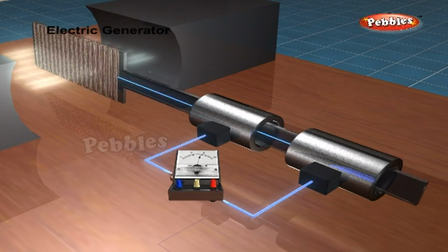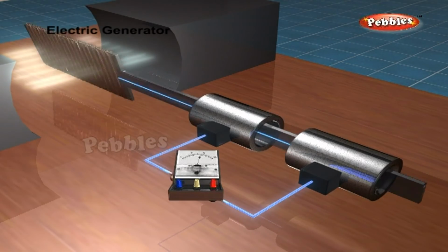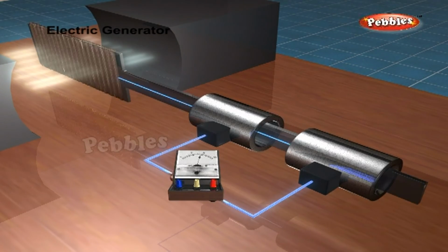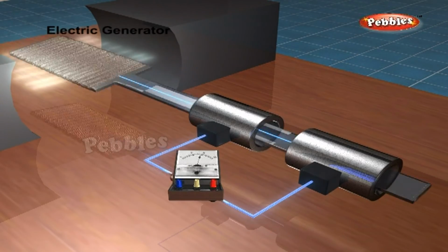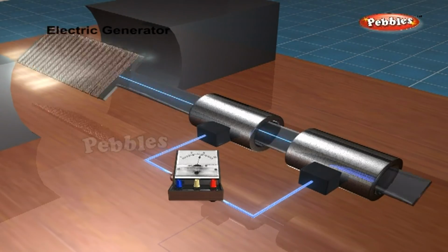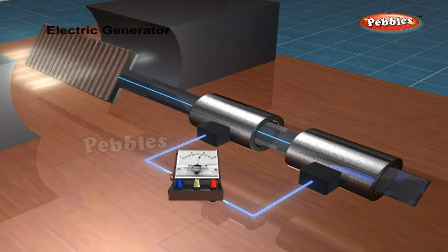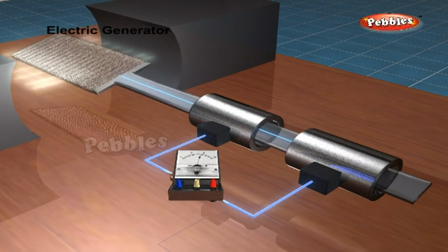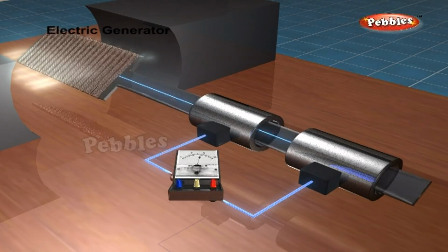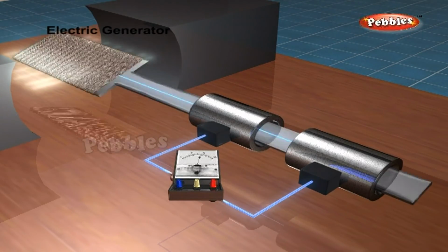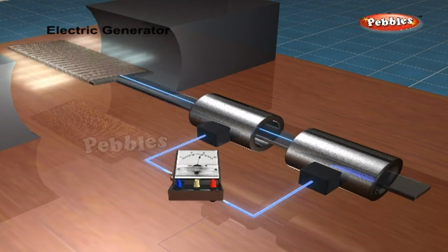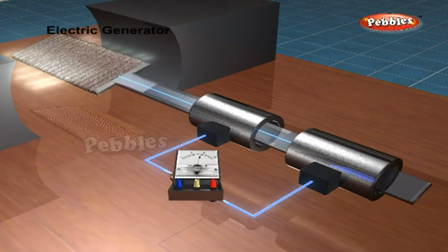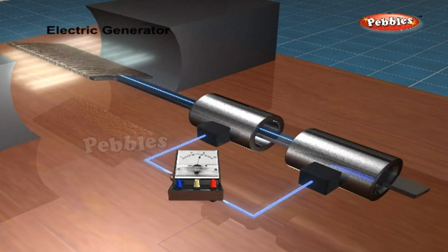If there are a large number of turns in the coil, the current generated in each turn adds up to give a large current through the coil. This means that the current in the external circuit flows from B2 to B1. After half a rotation, arm CD starts moving up and AB moving down. As a result, the directions of the induced currents in both the arms change, giving rise to the net induced current in the direction DCBA. The current in the external circuit now flows from B1 to B2.